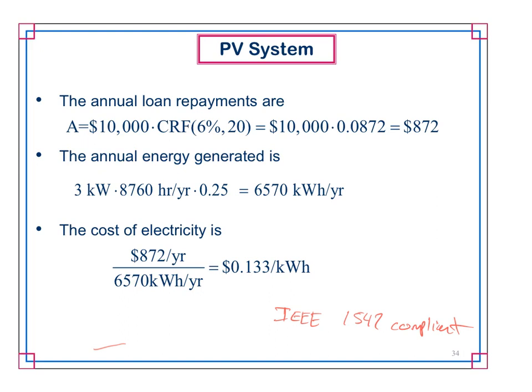Okay? There are different configurations. Yes, you can work with DC systems, and you can have inverters that don't necessarily rely on the grid, but you cannot interconnect to the grid. And believe it or not, by far the most efficient, most reliable, most cost-effective way to get 24/7 power is from the grid, not from your PV system. You're going to hate to hear that. So that's why, for people who have camps, one of the things that makes a camp very viable is a utility line that runs out to it. Having no utility line, even with solar for lights and all that, is a very different experience than having a utility line that goes to a camp.